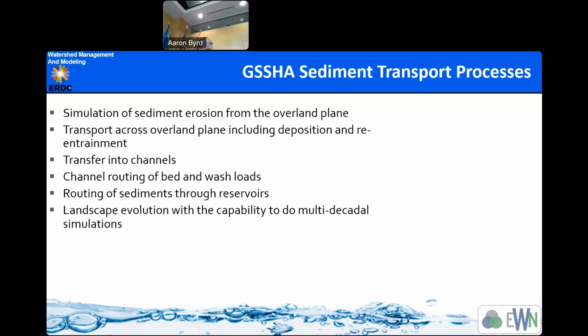After the overland mass of sediment is transported with some routing equation, it goes to the stream. And in this stream, like the hydrology portion is 1D, there is a process that transports the sediment from one link to another and towards the outlet. But if there is a reservoir in between, then it has the mechanism to deal with the sediment in the reservoir as well.